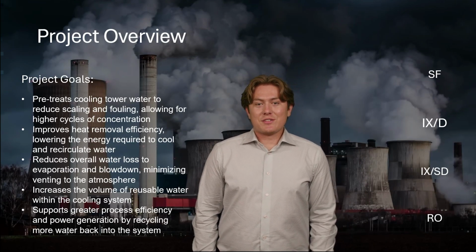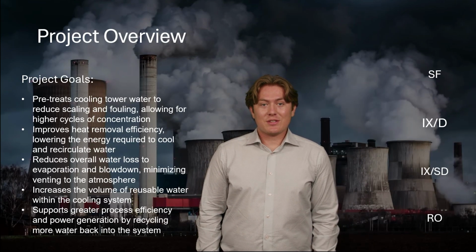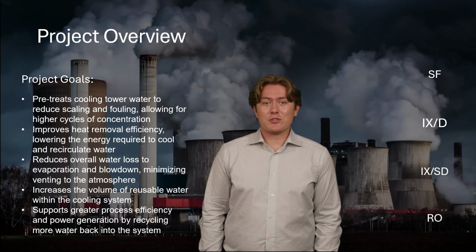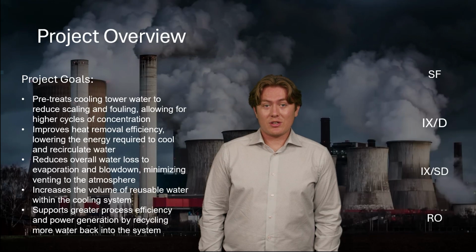Our process design is comprised of a treatment train of multiple water purification unit operations, designed to limit the dissolved substances entering cooling towers. The five primary methods of filtration selected for this process were sand filtration, reverse osmosis, ion exchange with demineralization specialization, as well as ion exchange with heavy metal specialization.